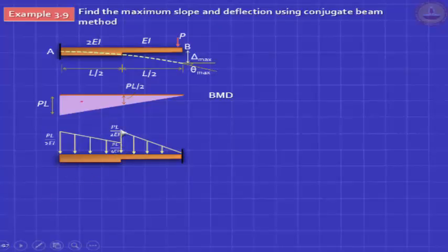Okay, so that's all. This arrow becomes halved on this side, and the right side, this PL you have to divide by 2 EI. So this will have the same height as this. That's the story. So you're right, this is a trapezoid and this is a triangle. So what? You don't care. You get what you get and it's easy to find your support reaction. The moment you get your support reaction in your conjugate beam, you've got the answers. You've got your maximum theta and delta.